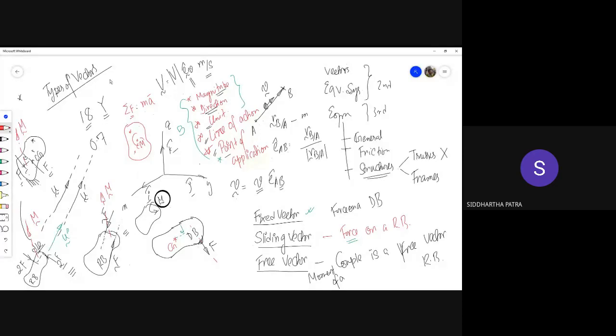Now there is an additional equation. So this is the linear momentum balance equation. Now there is an additional equation, angular momentum balance, and there the summation of all the moments due to all the forces, so all I'm doing is Ri cross Fi. But this time Ri is being measured with respect to some point O. And that is going to be that I matrix that we talked about, again calculated with respect to O, times the angular acceleration.